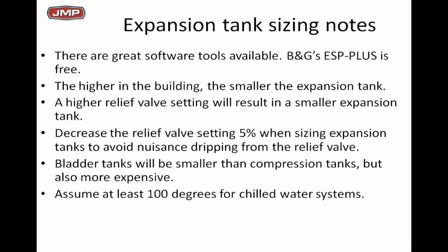We would recommend setting the max pressure at the expansion tank about 5% below the relief valve pressure. In other words, if I had a 100-pound relief valve in my system, I wouldn't want to take the system pressure any higher than say about 95 pounds. These valves are going to start weeping a little bit before you get there, and you want to give them a little bit of safety room, 4 or 5 pounds, so about 5% when you go sizing expansion tanks.